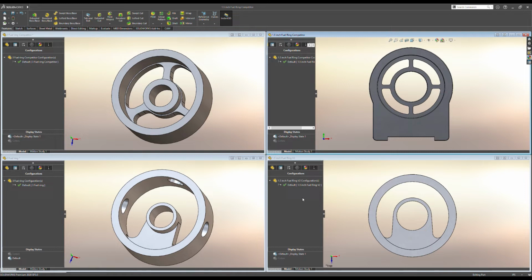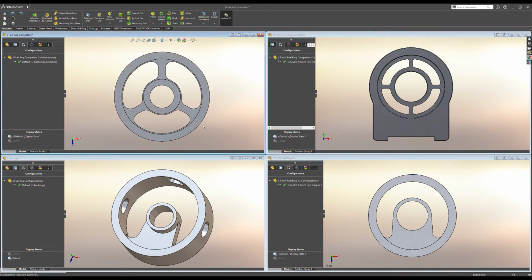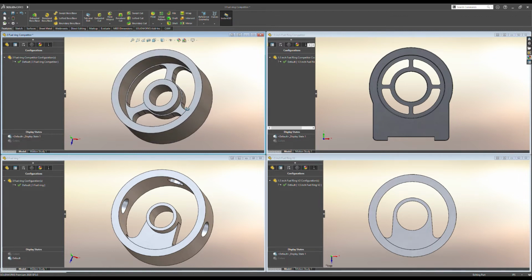And this is particularly the case with a generic fuel ring design. Like you can see here, there is a large amount of material that is restricting airflow. What that means for the burner inside the regen and the fire tube is a fuel-rich scenario. In terms of an air-fuel ratio, we have a good amount more fuel than a standard stoichiometric air-fuel ratio, which means that the emissions are going to be higher and we're not going to get a very efficient burn.